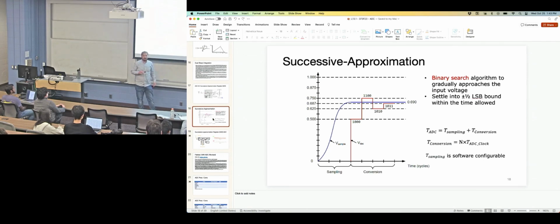Does that make sense? So there's not a big value to creating a thing that says, okay, you're within a certain threshold, let's just stop conversion, because you don't know when that's going to happen. So from a system level, it's not like you're going to choose to take an ADC read faster again. It wouldn't give you much advantage. The hardware makes no decision to stop converting because there's no advantage to doing it.